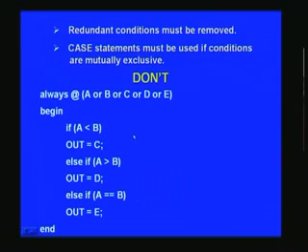This is another case where redundant conditions appear, and you will have to remove that. You have to identify where the redundant case is and remove that. What is redundant, we'll have a look at this. And don't follow this type of coding, right? If you do, you will create an additional mux and hence additional delay, and that in turn will slow down your frequency of operation. And how it does, let us see.